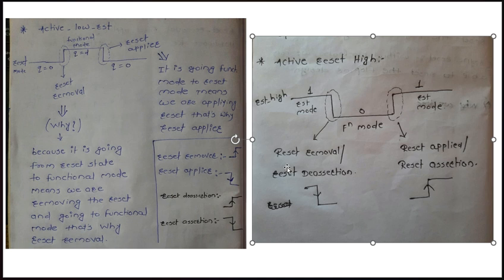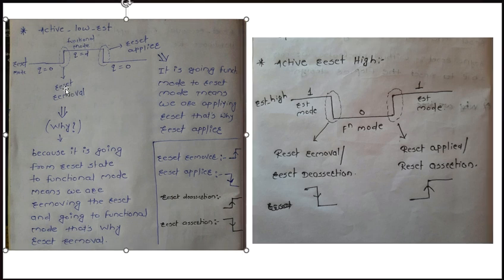Here we are seeing these terms: reset removal, reset deassertion, reset apply, reset assertion. So what is the meaning of all those things? First, what is meant by reset removal? The definition is in the word itself. Whenever we are removing the reset, going from reset mode to functional mode, then that is called reset removal.